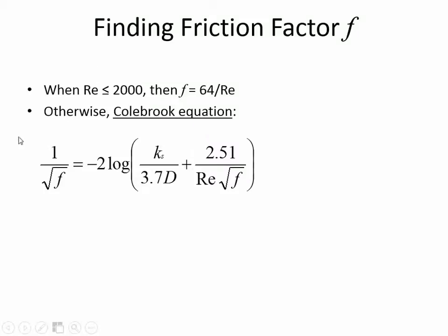But otherwise, in any other Reynolds number above that, the Colebrook equation will always be valid and relatively accurate. It's the most accurate way of finding the F value. I'll be introducing 3 different equations today for finding the F value. Colebrook is the most difficult of those 3 methods, but it's valid over the longest range of flow conditions, and it's the most accurate. So it's an investment.